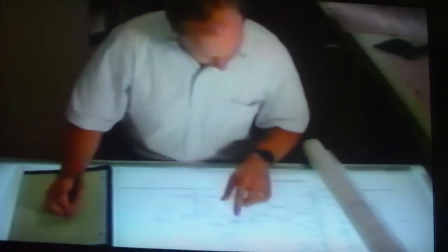Once you have the right tools, a location survey will help you find out whether or not you have a harmonics problem and where it's located. Walk through the building. Look for personal computers and printers, adjustable speed motors, solid-state heater controls and dimmers, and fluorescent lighting fixtures equipped with electronic ballasts. If this type of equipment is present, chances are the electrical system contains harmonics.